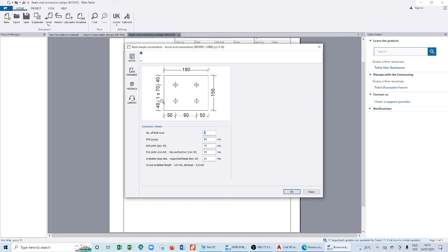Now you have to take into consideration that if I put the edge of the bolt to here to be so small, what will happen here is it can easily shear off. Because with time, that bolt can wear off. You find the hole is enlarging. Then at one point it can just tear off the bolt.